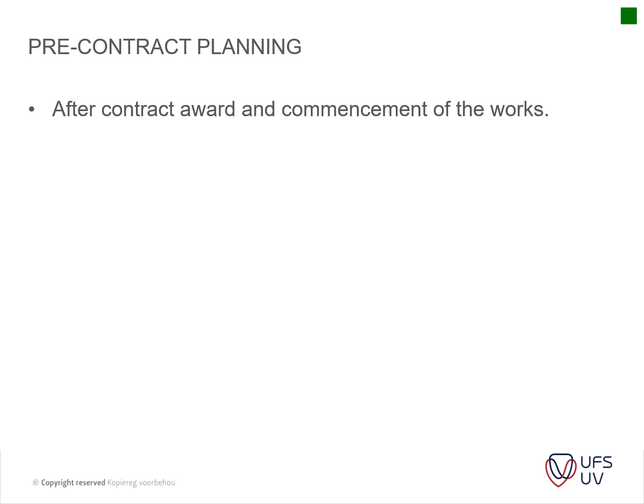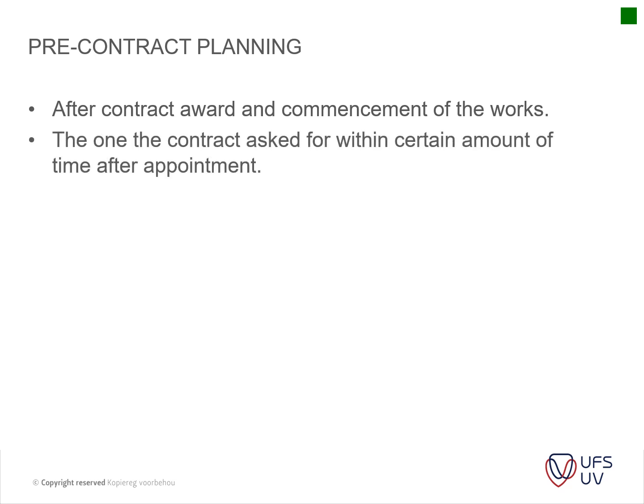Usually you get notice that you have to be on site within 2 weeks, or within a month, and within that time you have to do a lot of planning. You might have a handover meeting from your consultants to transfer the information to you. You need to draw up your health and safety plan, your program, etc.